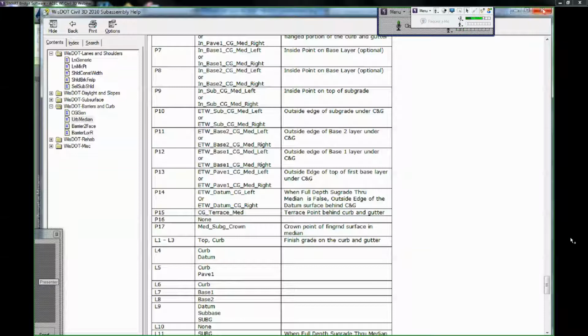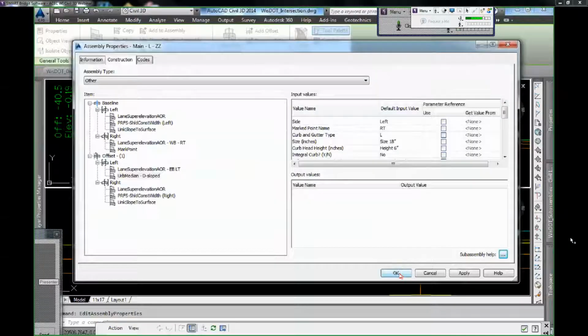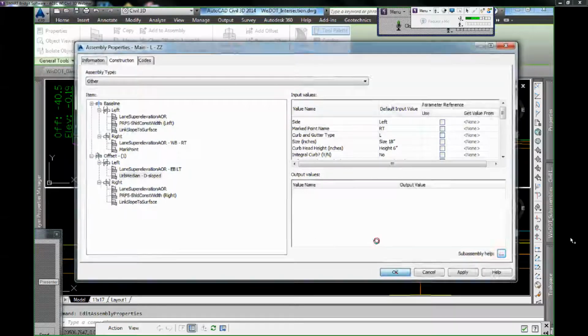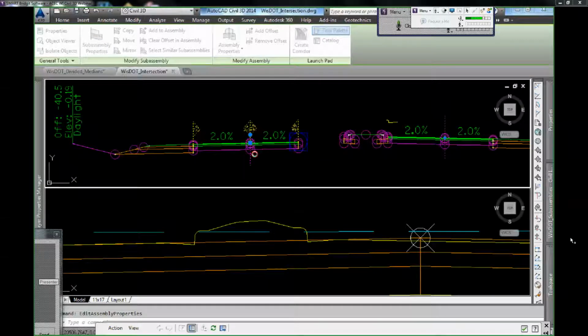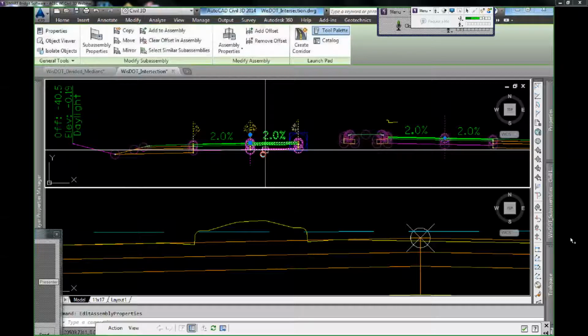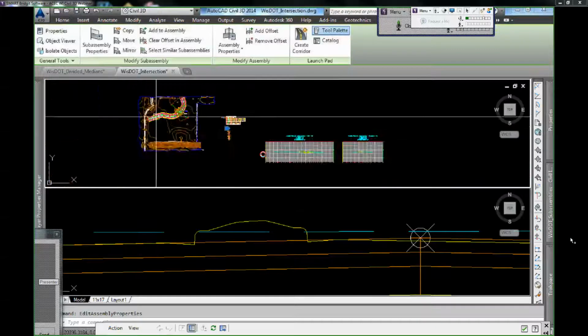Yeah, and there are other areas where using the links in the surface definition does add value. It can positively affect triangulation of your surface, especially in the intersections with those curb fillet regions, for example. When it transitions between the main road and the side road, some of that triangulation occurs across, in a perpendicular direction to the way we want to see it.